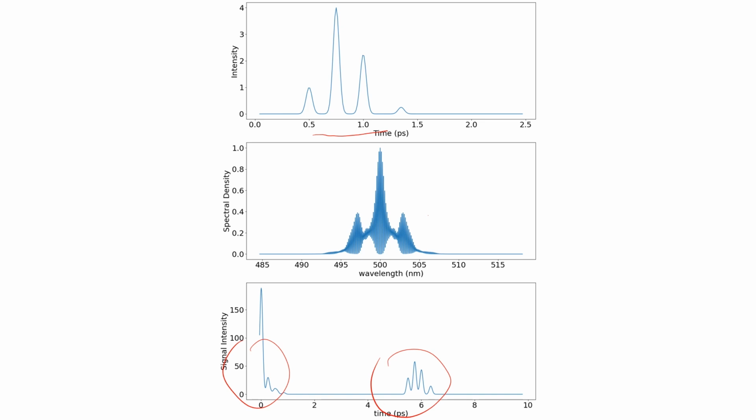Now the signal has been blurred because the reference signal in this case is a 100 femtosecond long pulse, and so that acts as the impulse response for our measurement of the reference, and so the reconstructed signal is blurred by this interference with the reference. Now, so we've seen two different methods for characterizing temporal signals by holography.